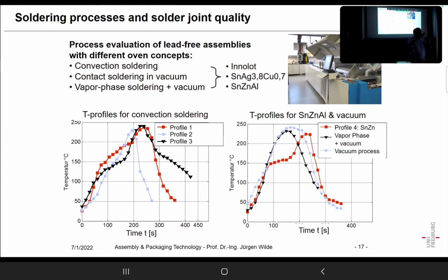But as it is a fixed point in condensation, we can say the temperature will never go beyond 100 degrees centigrade when we have condensation of boiling water. Okay, that's something very good. First of all, we can transfer lots of heat with that phenomenon. And on the other hand, we are absolutely sure we have no overheating. The temperature will not go beyond a certain point.